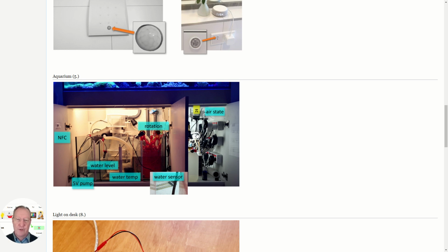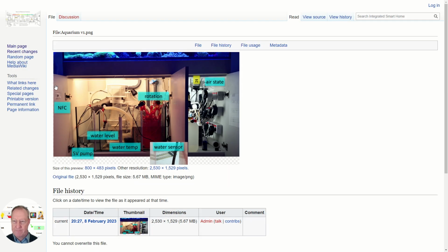And so the Raspberry Pi actually controls the heater here. So when the water temperature drops below a certain level, the heater is switched on. And once the water is warm enough, the heating will be switched off again. So I'm not using the mechanical kind of stupid thermostat in here. I can control the heating and the water temperature by the Raspberry Pi.